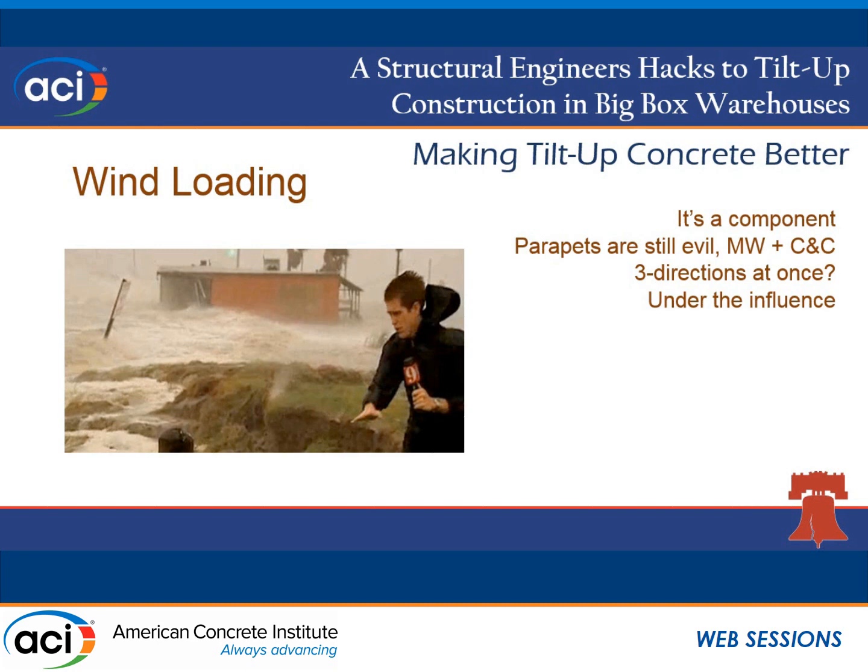The other thing on wind loads that comes up, more specifically in connections, but don't forget, in a wind load scenario, you're going to have loading in 3 directions at one time. Right? You're trying to develop or check the in-plane connection to develop your in-plane diaphragm shear into your in-plane shear wall. Don't forget you also have uplift and side wind pressure at the same time. So if you've got one component that's doing all 3 things, make sure you've accounted for them all.